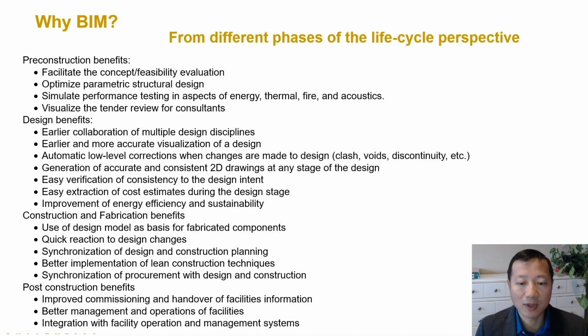Synchronization of design and construction planning. This is the part where we talk about 4D, 5D modeling and the cost and progress or time management. Better implementation of lean construction techniques. With a BIM model in place, you know exactly when, what will be used at which location for what part. So this allows you to better facilitate and coordinate the logistics with suppliers and vendors to implement the just-in-time concept. Also, the synchronization of procurement with design and construction.